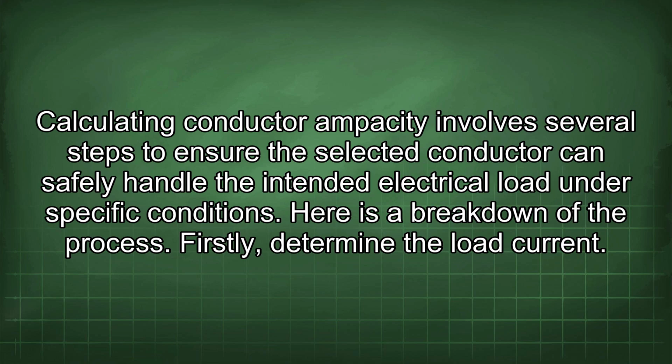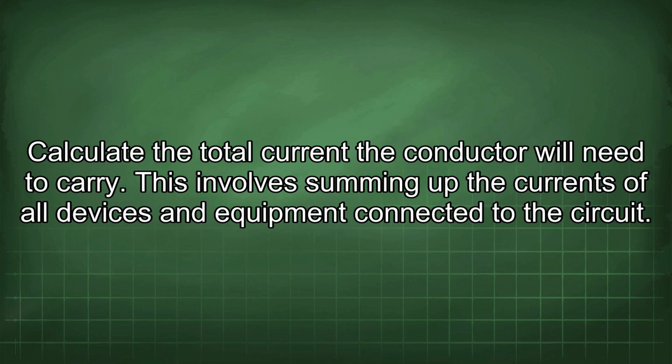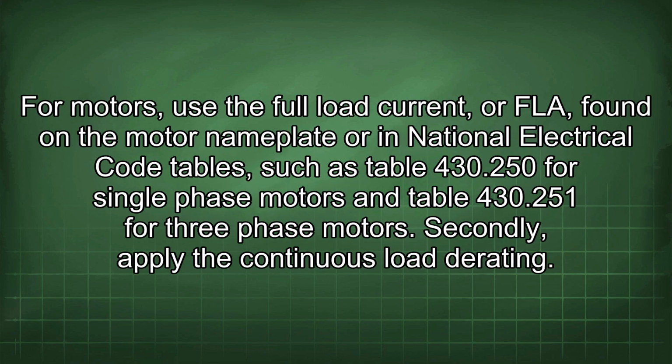Firstly, determine the load current. Calculate the total current the conductor will need to carry. This involves summing up the currents of all devices and equipment connected to the circuit. For motors, use the full load current found on the motor nameplate or in National Electrical Code tables, such as Table 430.250 for single-phase motors and Table 430.251 for three-phase motors.